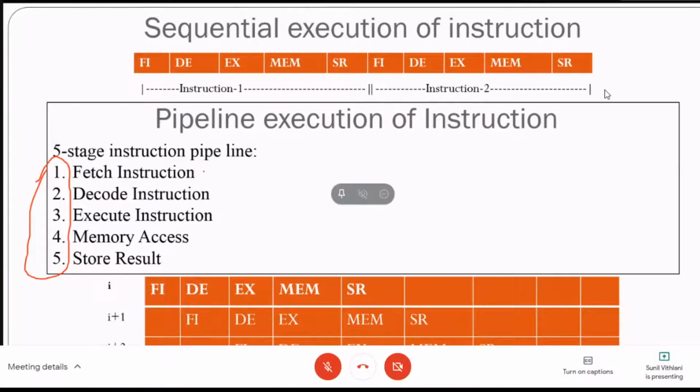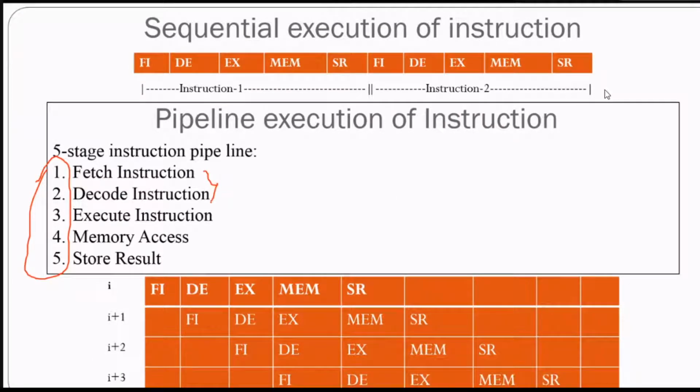It might be possible that suppose if your instruction is jump instruction, तो उसमें execution और memory access आएगा ही नहीं. वो पहले instruction fetch होगी, decode होगी, और decode होगी तो आपको पता चलेगा कि this is a jump instruction. So it doesn't require any other thing. It will directly just store your address into program counter, and then it requires just only 2 stages.